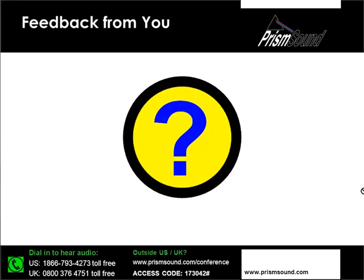I've given you 5 different options. Those of you with a PC will see these options on your screen. Firstly, we could increase the FFT size, we could decrease the sample rate, we could use some averaging, we could increase our audio level, or we could use a larger screen. Which of those options do you think will help us to improve, enhance our FFT resolution? I'd be grateful if you could select your options as quickly as you can, and in just a second we will once again take a look at the results of our anonymous survey, and I'll give you just a couple more seconds to consider your options.